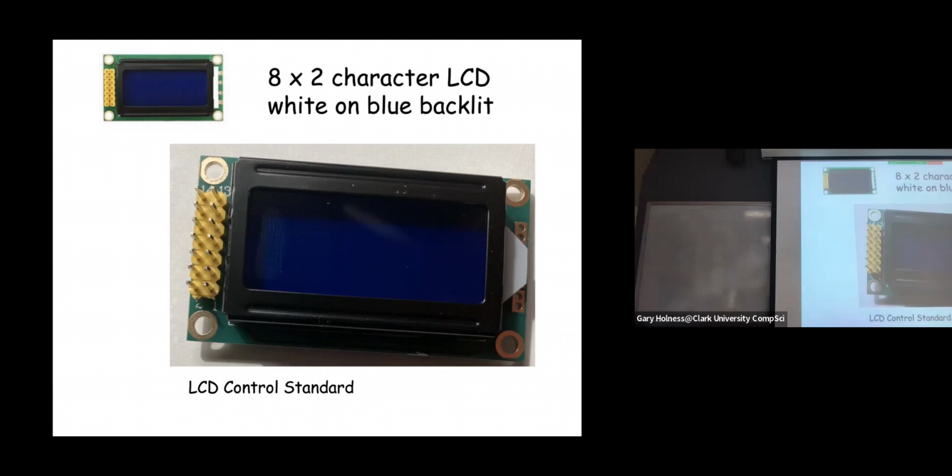And so if you were to design any kind of system that used the display, one of the huge considerations is the so-called power budget. You want to decide, do I run this off of the equivalent of 2 AA batteries, or do I have to run it off of something like a lithium polymer LiPo battery? And so that also affects, if something is mobile, the amount of battery life that you have if it's a bigger power budget.